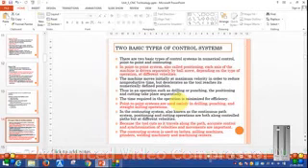In the point to point system, also called positioning, each axis of the machine is driven separately by ball screw depending on the type of operations at different velocities. Then point to point systems are used mainly in drilling, punching and straight milling operations. Because as the tool cuts, it travels along the path, accurate control and synchronization of the velocities and momentums are important.